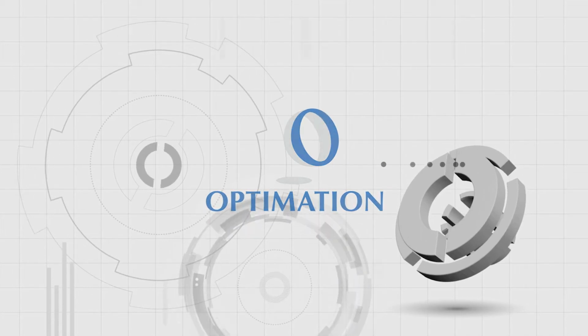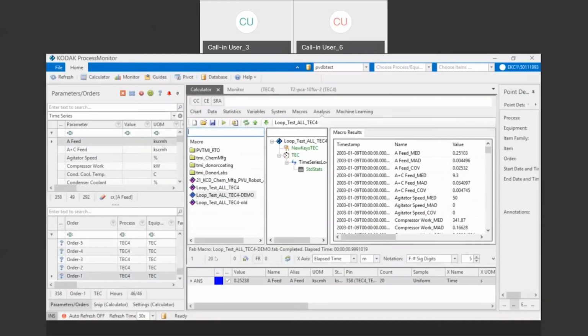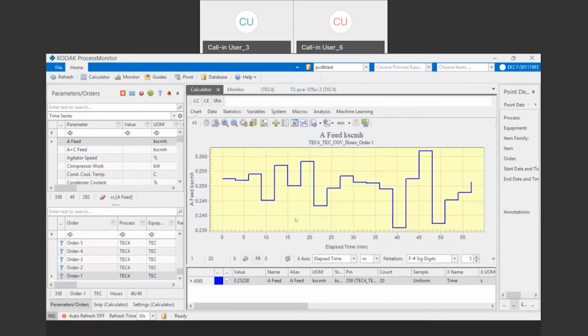So basically, when you look at it, we would show a time series, and the scan rate is once every 3 minutes. It's interesting, Dan and I were talking about this. Depending on the process and the fundamentals, chemistry, physics, and all that, this is relatively slow. We tended to do more like 1 hertz, or in some cases hundreds of hertz.